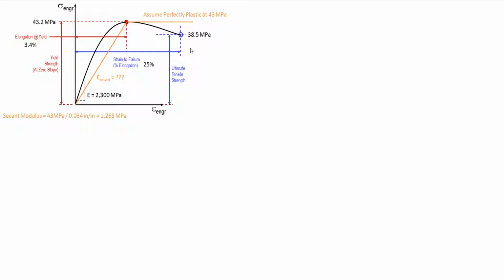We usually don't design our parts or machines around the plastic deformation region. Imagine a CNC machine, a manual mill, or a manual lathe machining a piece of steel, and all of a sudden a piece of it bends and you're no longer square or trammed.